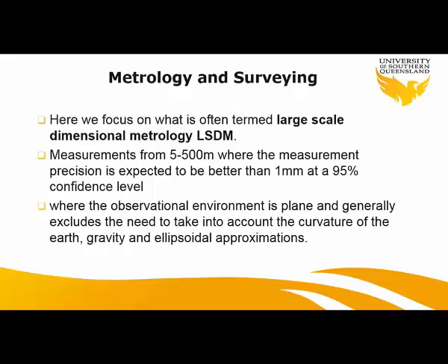Here we want to focus mostly on large scale dimensional metrology, or LSDM. Basically, this type of metrology is for measurement of anything within 5 meters to 500 meters distance, and we want to achieve an accuracy of 1 millimeter at 95% confidence level.